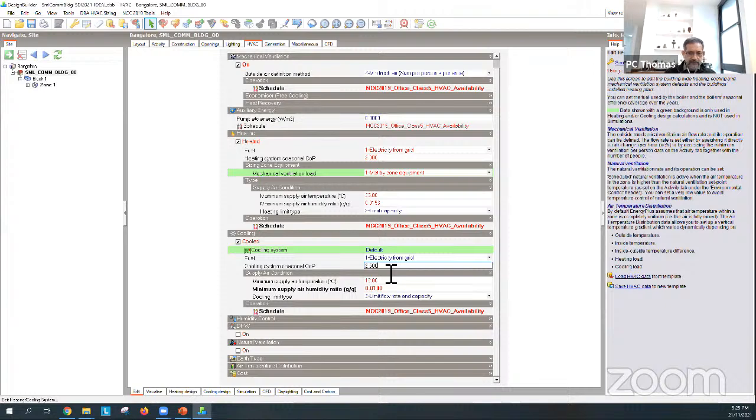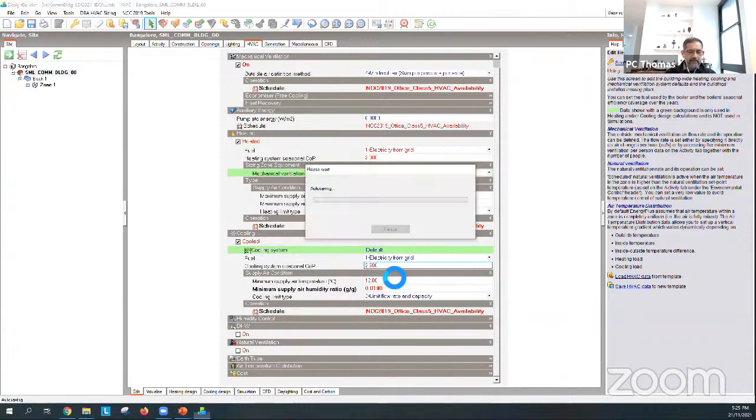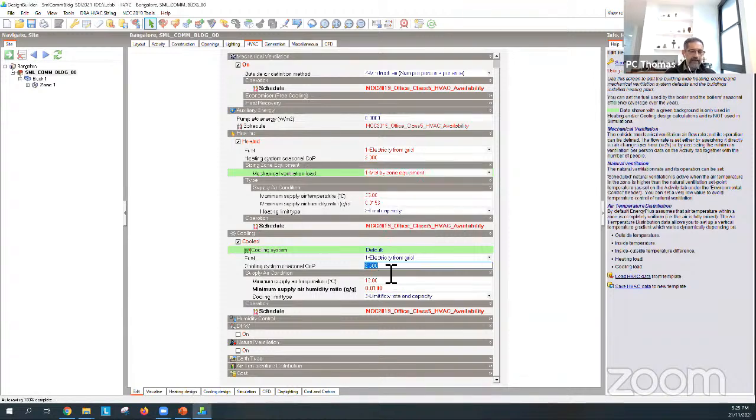So it's like an efficiency, but it's not exactly, because the COP is more than 1. And the reason it's more than 1 is because you're not comparing apples with apples, or you're not comparing the same two things. You're comparing how much cooling energy can be delivered by supplying 1 unit of electricity. So they are both energy, but they are two different kinds of energy.